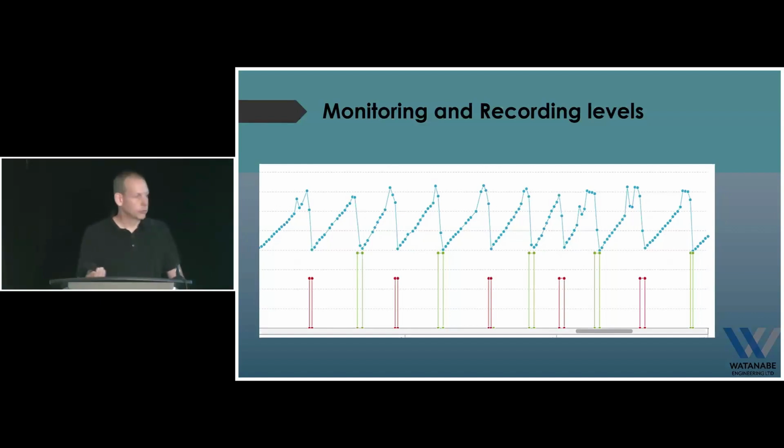And I'm sure most of you have figured out that just because the pump's got rags in it doesn't mean to say it's going to trip out. It's going to keep running and wear out your wear rings really quickly. So if you're relying on your hour meters, you might be running this pump for a couple of weeks before you actually notice any significant difference in the pump run times. Whereas if you look at this screen, you can see it instantly.